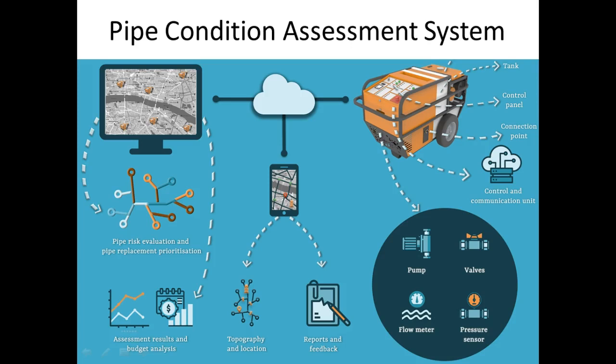And the third thing that they do is basic maintenance. If it's just replacing a small cover on a water meter, then they can do that in the field so that you do that basic maintenance. Part of that is also just opening and closing valves. You're supposed to exercise a valve once a year in a system. Just open and close it to make sure that it's not stuck and that it operates fine and so on. So this is all combined in that process.